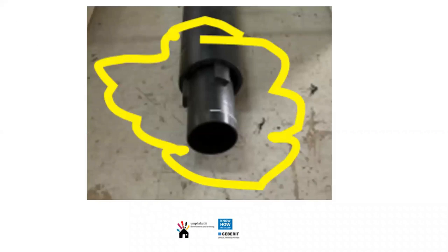So what does that look like? Our outer pipe would be the 160, and a lot of the engineers, as I say, this document is an old document, and they're starting to look at the other products that are available. So we're using a PN10 or PN12 outer. Then we use a 110 HDPE drainage pipe, so similar to the Geberit HDPE. And onto that pipe, we weld these 3 spacers. And that allows the pipe to be turned in any direction, and the invert will always be correct, as it fits quite snugly into the 160.